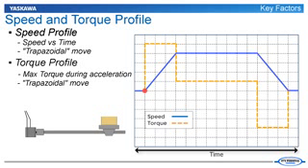The torque at the beginning of the trapezoidal move is highest because mechanical friction must be overcome and because the load must be accelerated from rest. This point of highest torque is called the max torque. Once the traverse speed is reached, a nominal level of torque must be applied to overcome friction and maintain speed. To decelerate the load, often a reverse torque is required.